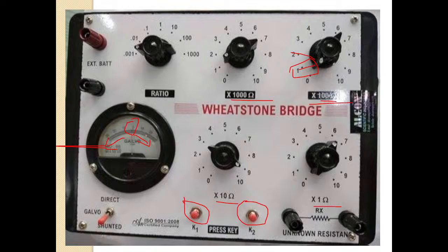You can see this is a zero deflection scale. This is 0. If the deflection is further increasing, don't increase this. Don't vary this knob. You go to some lower value around here. You can see 10 is there. So you just increase from 0 to 1, so you will get 101 ohms. Check whether the deflection is towards the 0 or away from the 0.